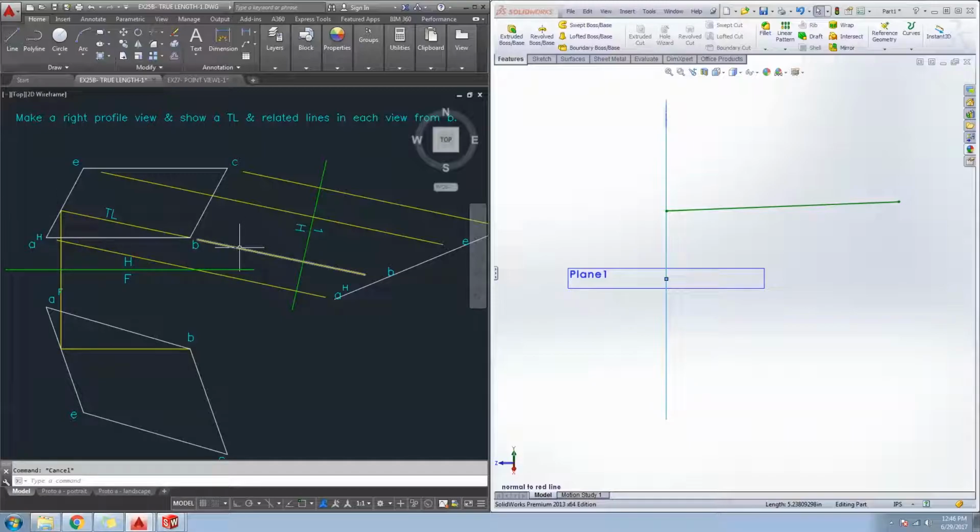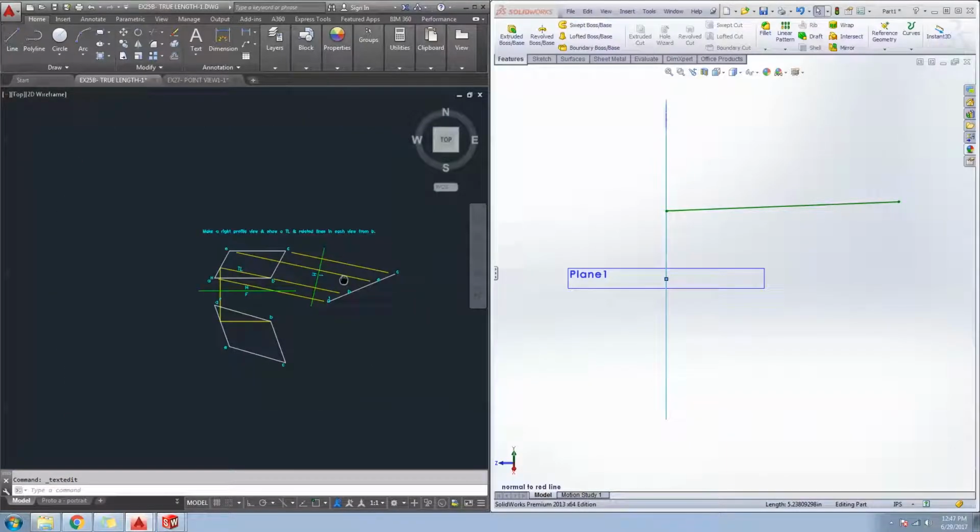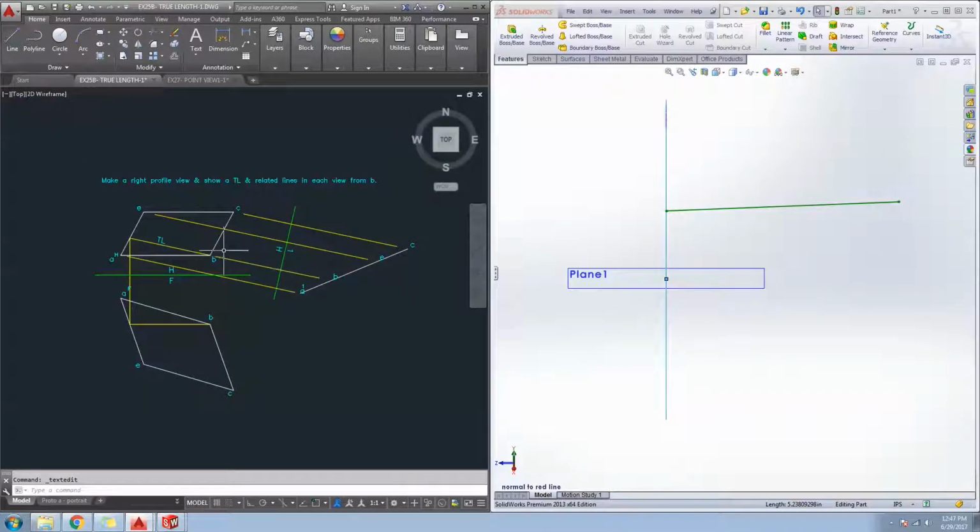These projection lines are not actually portions of the geometry. This is actually a reference line that I'm using to construct this view over here. It establishes the direction that that view is going to be looking at this plane from. However, these guys are not actual geometry. These are just references to help the viewer track. Oh, from point A to point A. Oh, that must be point A over there. So that's why some points are connected and some points are not.